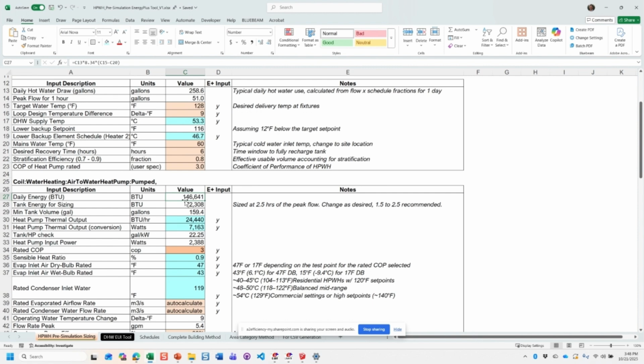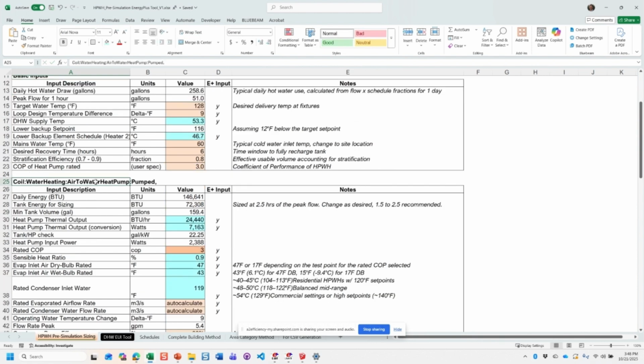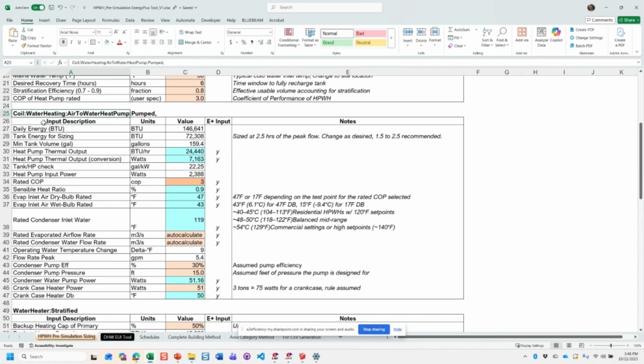So down here, now let's get into the basic inputs. I didn't even put a category here. I guess we'll call them basic inputs to start to go through the components. And I apologize, these fields are not in any specific order. I arranged them a little bit before I made this to try and group them, but this is not the object in EnergyPlus. These are the hand calcs you have to do, arranged in a logical format so you can work top down. So for this one, we're really working towards how big is the compressor?